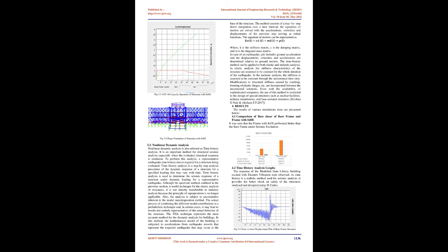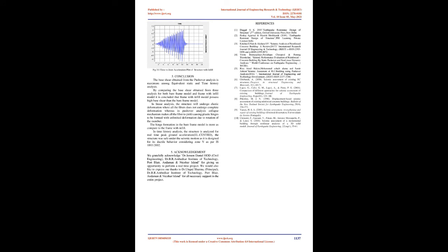With the increase in magnitude of lateral loading, the progressive nonlinear behavior of various structural elements is captured, and weak links and failure modes of the structure are identified. In addition, pushover analysis is also used to ascertain the capability of a structure to withstand a certain level of input motion defined in terms of a response spectrum. Pushover analysis is of two types. I. Force controlled.